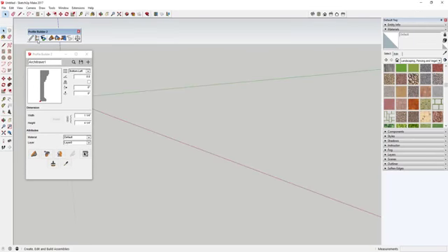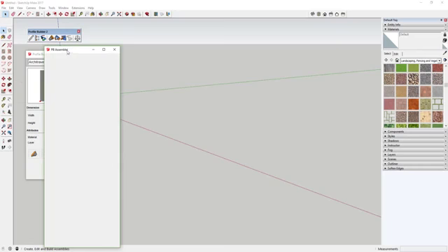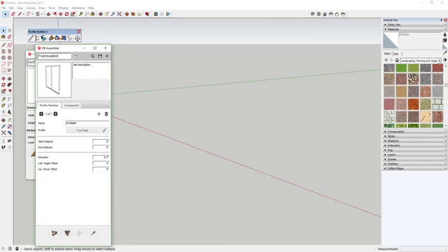So I think what we're going to do is start off and go into the assembler dialog. So what you want to do is go into the Profile Builder toolbar and look for this second option that says Assembler Dialog. When you put your mouse over it, it says this is where you create, edit, and build your assemblies. In this section is where we're actually going to build our whole wall. And so what you can do in here is add things like studs and sheathing and all that different stuff.